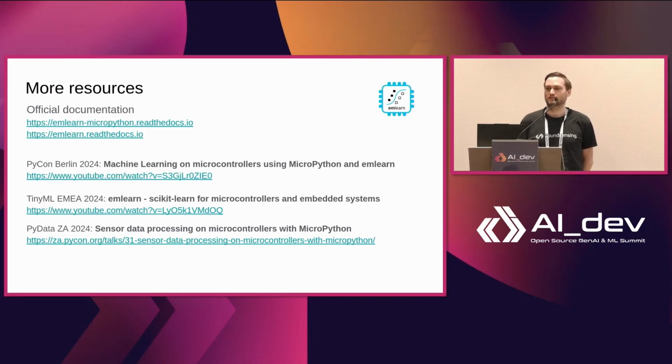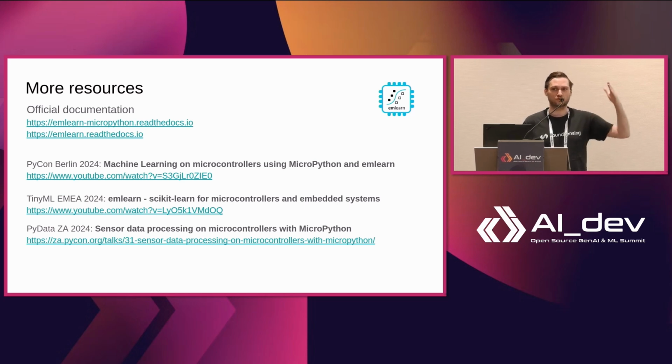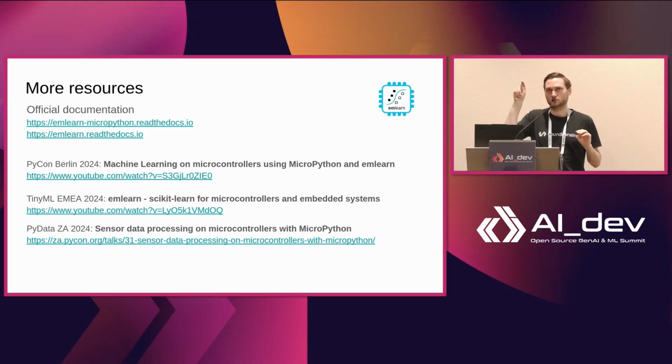Is it possible to move the weights to a separate EEPROM, or is everything in the flash? Yeah, is it possible to move the weights to a separate storage or EEPROM? Yes, you can. On the C library, when you generate the code, that's designed to go into program storage, just static. And most compilers have a special annotation that says put it in that reserved place. When you do the convert, you can specify these annotations so that it does the right thing. And if that doesn't do it, I think you could probably do it manually. So yeah, there's some support for that.